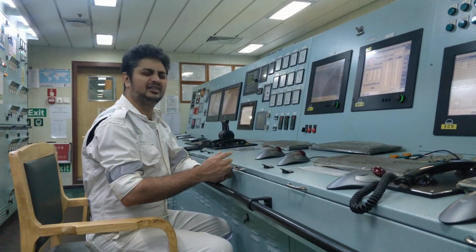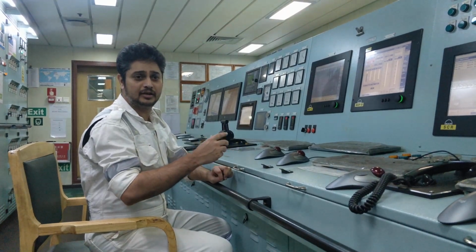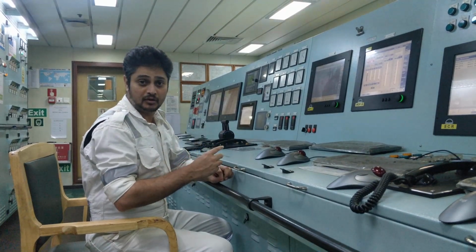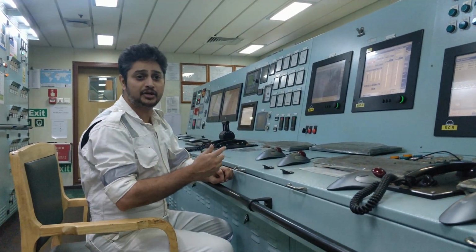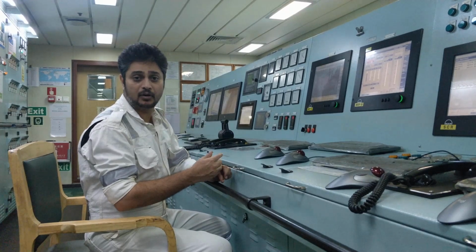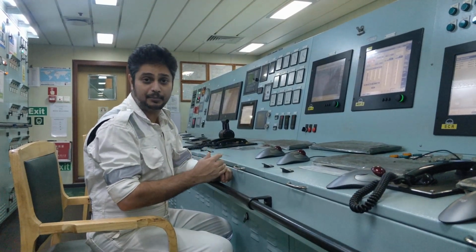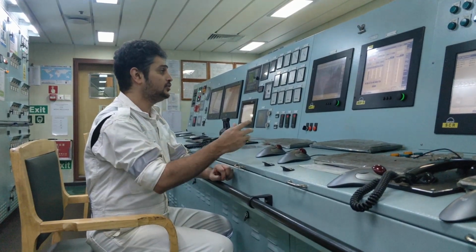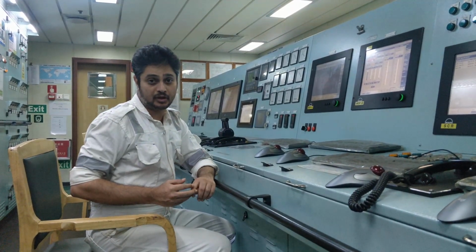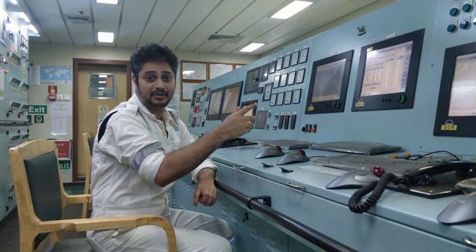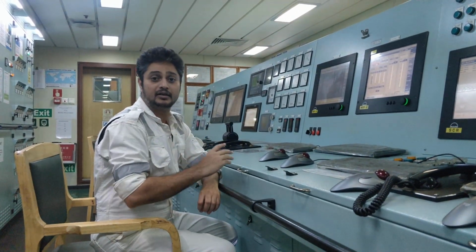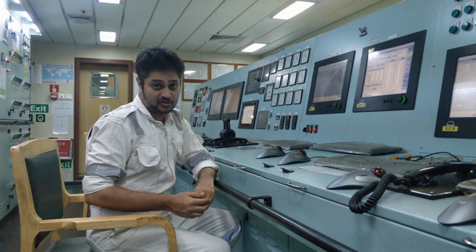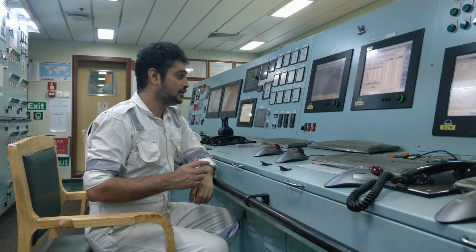The programming is basically done in the system. The engine timing in the CCU, when to inject fuel, when to open the starting air valve, all these things are pre-programmed in the ECS software. So this is with respect to the starting air. The command goes, the solenoid valve energizes and admits the pilot air, thereby the main air goes inside through the starting air valve.